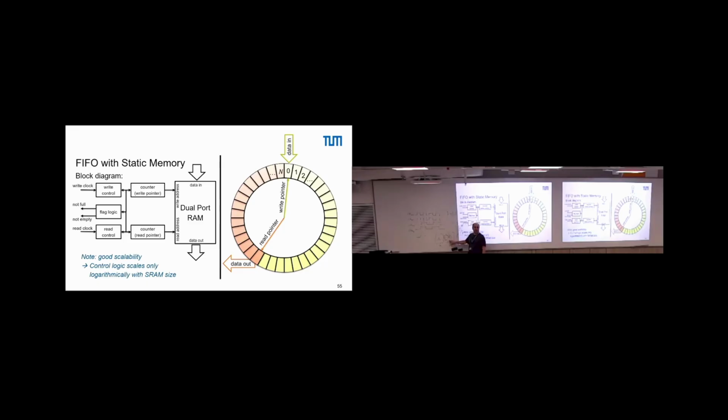Even if this here runs on a higher speed than that one. That's the first case. So even if they run on the same clock, those are different systems, you cannot necessarily rely that all data you send from one system to the other one are immediately processed. Then you need kind of a buffer, and there you use a FIFO.